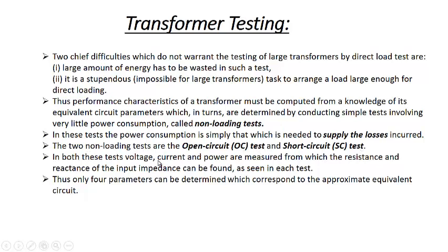In both the tests, voltage, current, and power are measured, and from these we can calculate the resistance and reactance of the input impedance, whether referred to the primary side or the secondary side. Only 4 parameters can be determined, which correspond to the approximate equivalent circuit.